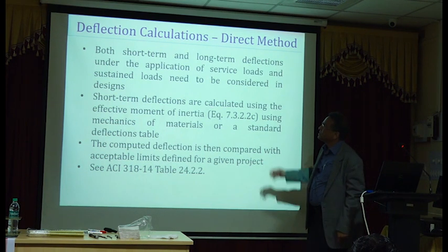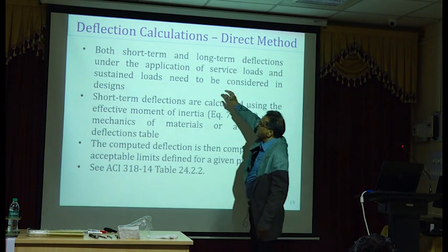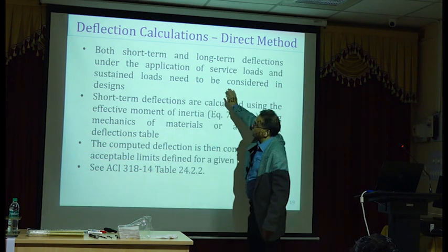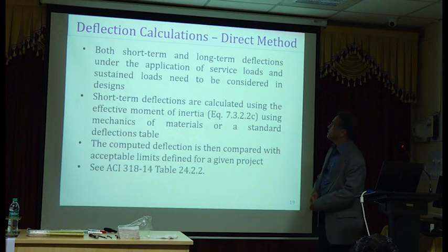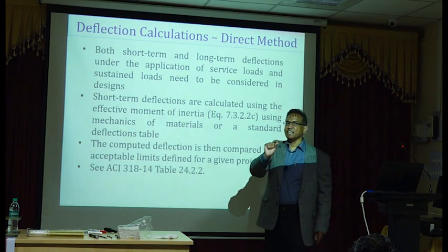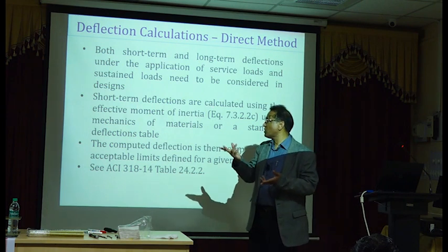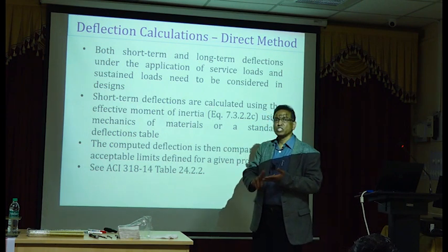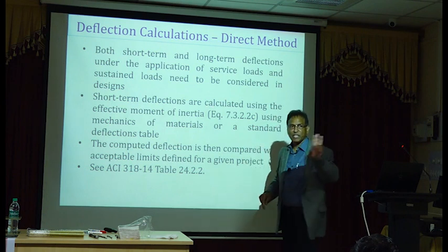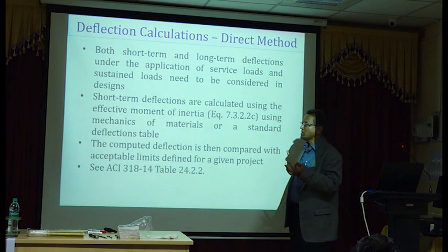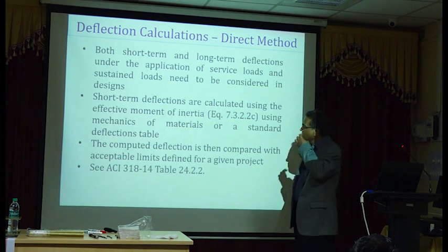So we will use sustained load contributions and we'll calculate the long-term effects. So we'll use the effective moment of inertia to find the instantaneous or immediate, that's what it's known as, immediate or instantaneous or short-term deflections. All three mean the same thing. Immediate, instantaneous, short-term deflection, all three mean the same thing.